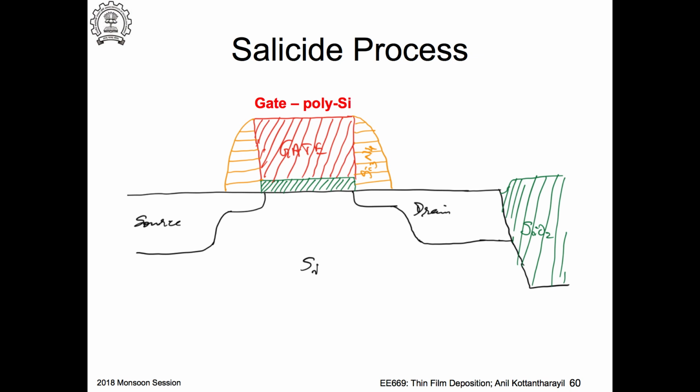So you have this process for depositing films. They'll actually deposit everywhere. So source, drain and gate are shorted. Okay. So she is suggesting that we should pattern this. We deposit the metal and then use lithography and etch out the metal from where you don't want it. Okay, so the other thing is lift off. Yeah.